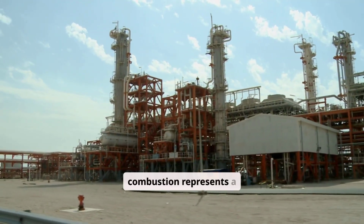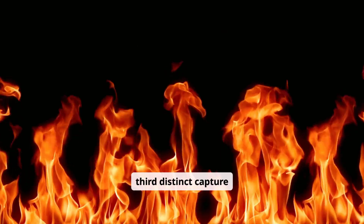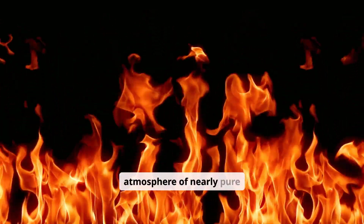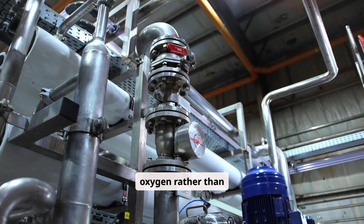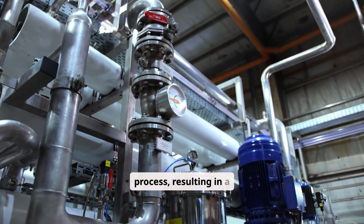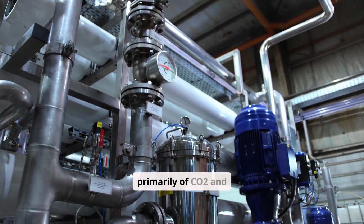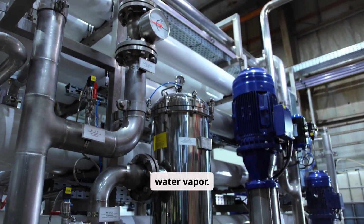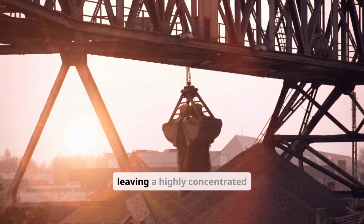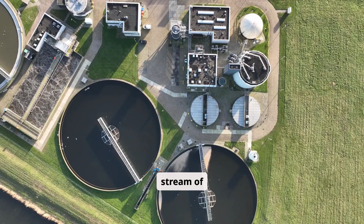Oxy-fuel combustion represents a third distinct capture strategy. In this process, fuel is burned in an atmosphere of nearly pure oxygen rather than air. This eliminates nitrogen from the combustion process, resulting in a flue gas composed primarily of CO2 and water vapor. The water vapor can be easily condensed, leaving a highly concentrated stream of CO2.